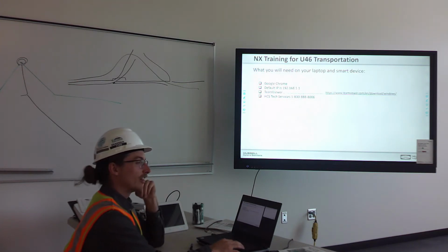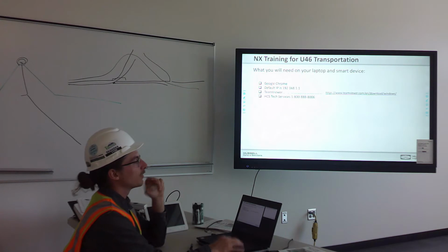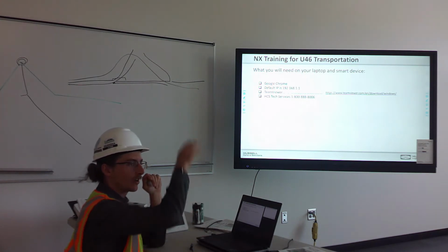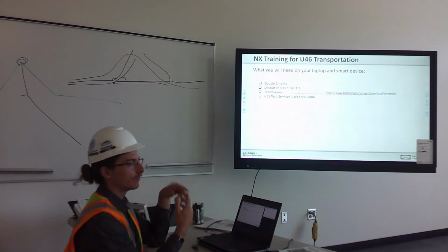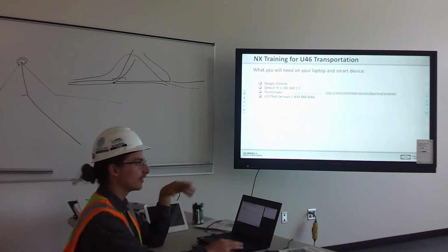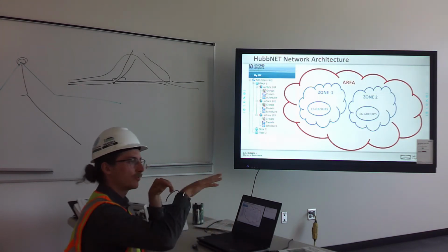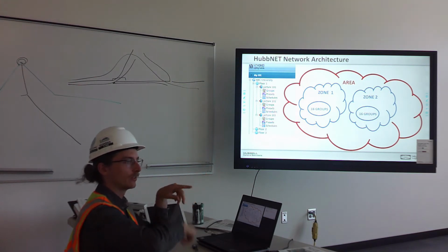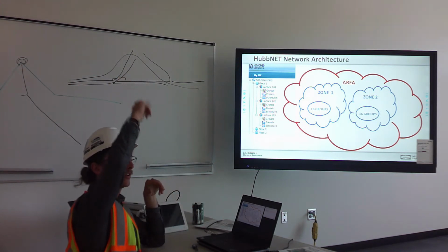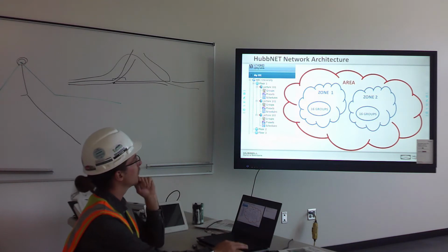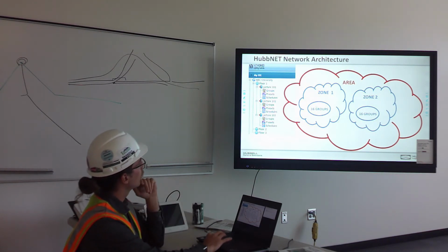You'll find that in the stairwells as well. That's another common area where all 3 levels are programmed into the same zone. And a feature of that is, if you trip one of the sensors on the first floor, it's going to tell all 3 floors to turn on because they're programmed into the same group, zone, and area.